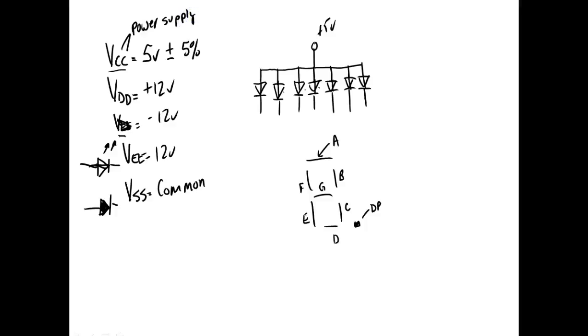Now, in solid state, you'll learn VCC is the power supply, VDD is the drain power supply, VEE is the emitter power supply, and VSS is the source power supply. But in digital, we just don't learn that. What we learn in digital is these letters represent these voltage levels. In solid state, these voltage levels can be anything. VEE could be common. VCC could be common. But in digital, these voltages have a meaning or a level that we deal with. So that help you?